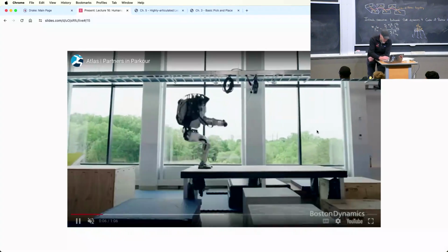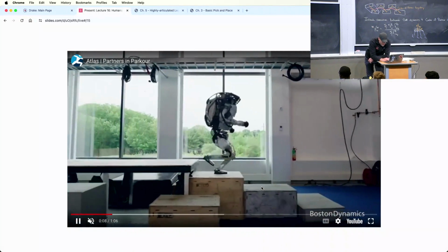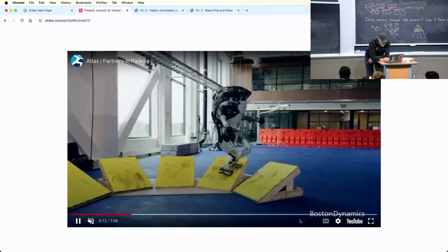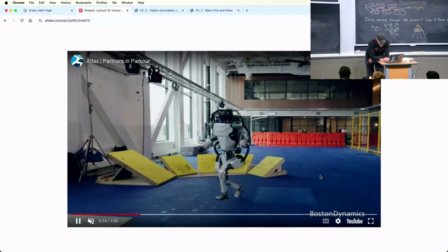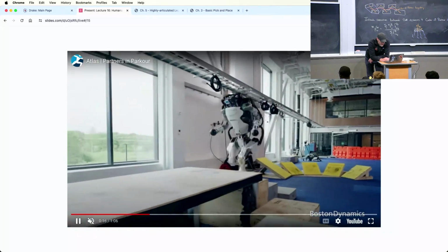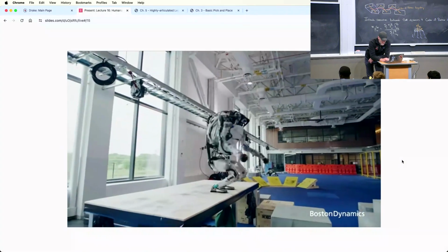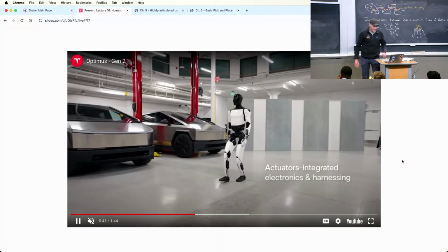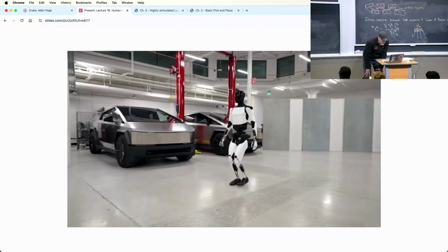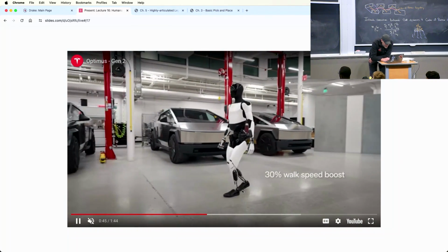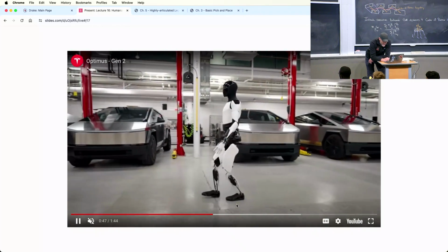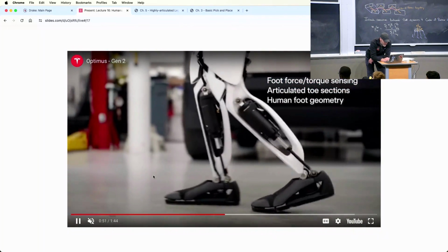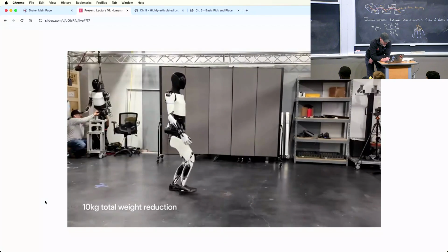So my understanding, not official, not sanctioned, is that they are roughly planning footstep holds and then doing nonlinear model predictive control to complete that. Okay, let's look at a couple of the others. I just pulled these down quickly. That looks like a ZMP walking gait to me. It's smooth and good, but it's, I think, a lot like what Asimov is doing.